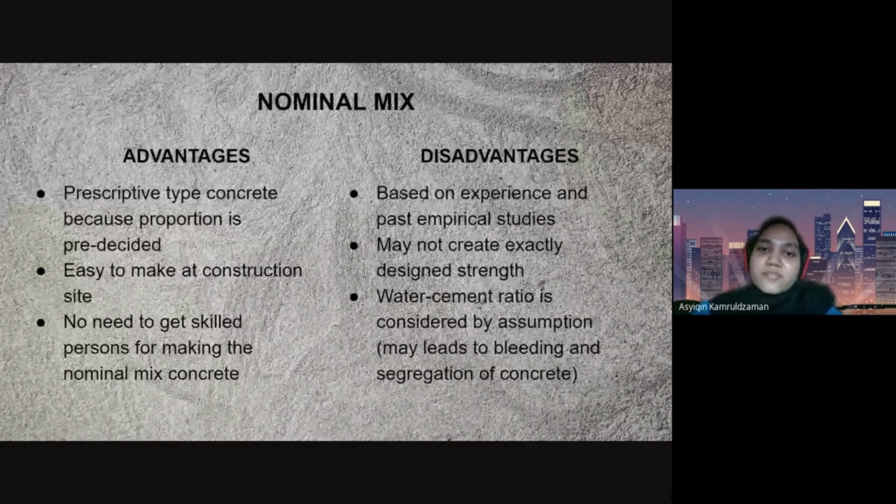And the disadvantages of nominal mix are that it needs to be based on experience and past empirical studies. And while doing this nominal mix, we may not achieve the exactly designed strength. And the water cement ratio is considered by assumption, which may lead to bleeding and segregation of concrete.